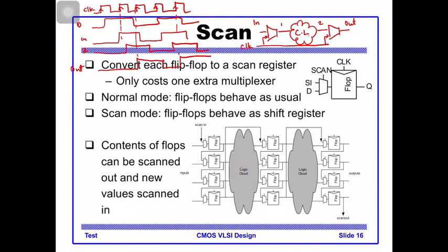So your flip-flop helps to control the timing of when the inputs go into the combinational logic, right? If you imagine there are many inputs going into the combinational logic, you can imagine that all this data is racing to go inside. In a race, they should all start at the same time to avoid the combinational logic having errors because some of the data is late.